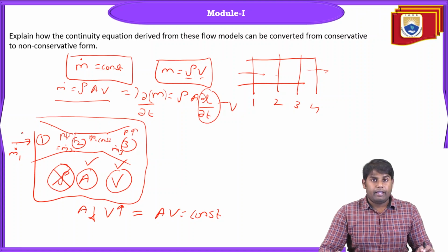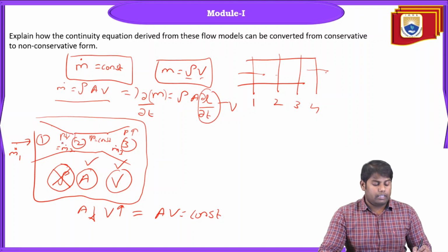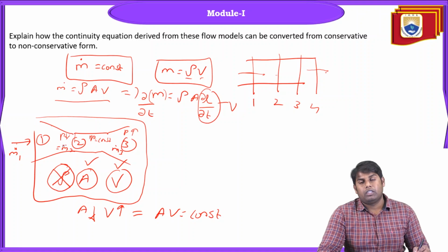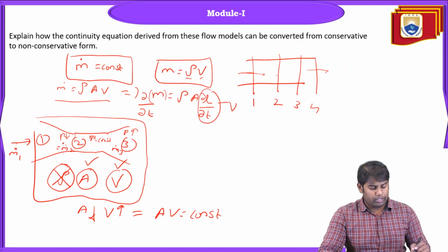So what is happening when we take the flow as incompressible, when we take this convergent, constant and divergent section? First, the pressure decreases. Why? Because area decreases, velocity increases. In the second section, what happens? It is constant. Why? Because there is no change in area. Third section, there is an increase in area, therefore increase in pressure and decrease in velocity. So this is what happens.